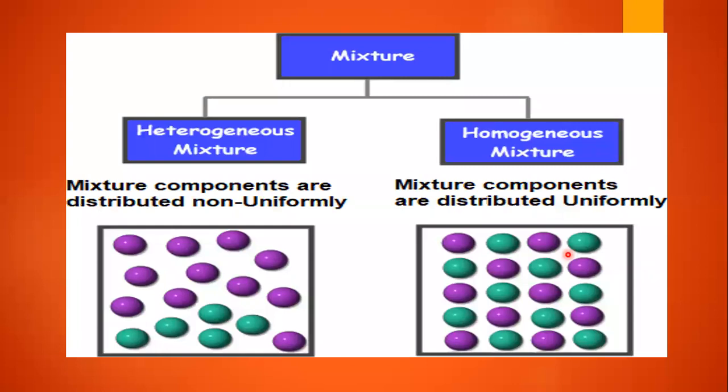Okay, so if we are going to maintain the engine speed at high pressure and high speeds, then we need a rich mixture, that means the actual mixture. The fuel-air ratio is going to be high, which means we are going to have more fuel here. So if more fuel is there in the actual mixture, 1 is to 12 like that is going to be there, compared to 1 is to 15, which is the stoichiometric mixture.